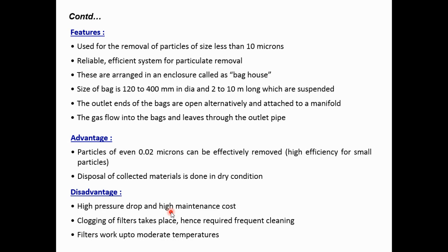If one bag bursts, it can contaminate all these things. Again you have to remove, clean, and manage that, and the cost of the bag filter is high. Due to the pressure drop, the maintenance cost is high. Clogging of the filter takes place and requires frequent cleaning, by mechanical shaking or jet, and if that is not working, then you may have a great problem.